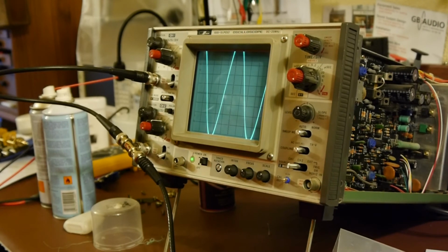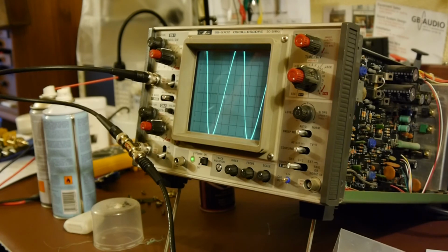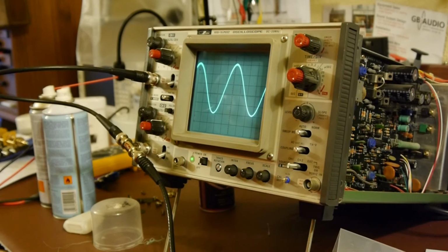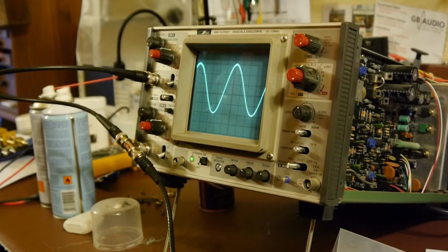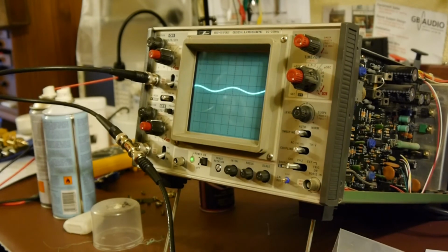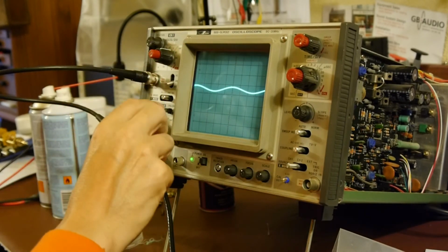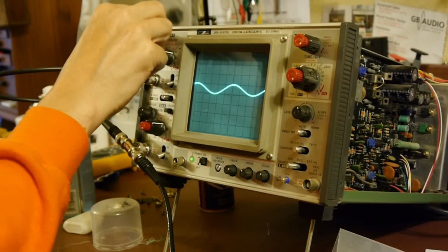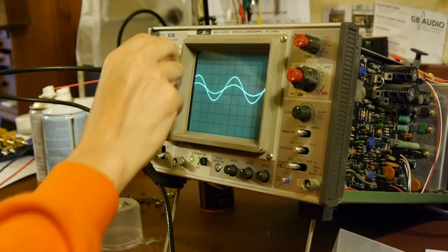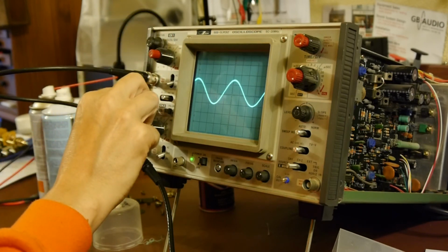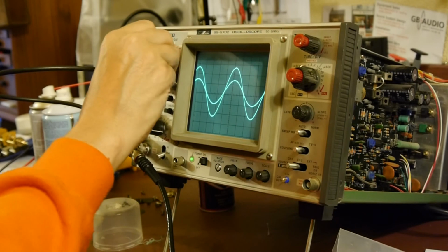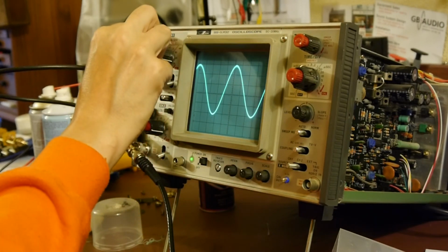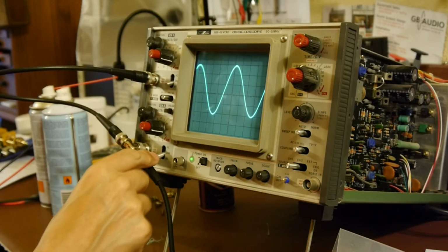Let's go to 0.5 volt now on the signal generator. Amplitude 0.5 volts. Actually, so let's do 50 millivolts. Amplitude 0.05 volts. So that should be 0.5 division where we are, which, yeah, it probably is. That should be 1 division. Two and a half divisions, which we've got. Next one should be 5 divisions. One, 2, 3, 4, 5, which it is, and finally.